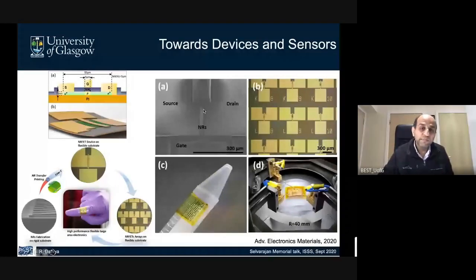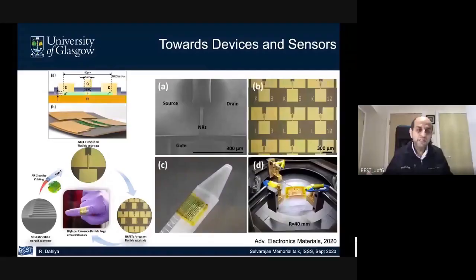These are the nanowires, the nano ribbons that you see here, source and drain, and they were then implemented. An array was obtained. We obtained devices with about 650 mobility, which is quite good mobility when you look at single crystal silicon based devices. In this case also they are single crystal, because the nano ribbon is taken from an SOI wafer. Those devices have about 700 to 800 mobility, and that leads to quite good performance, like conventional electronics. So this approach leads to electronics at par in terms of performance with conventional electronics, with the additional feature that it is flexible.